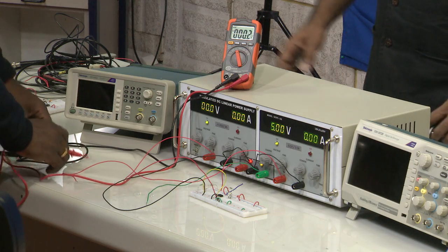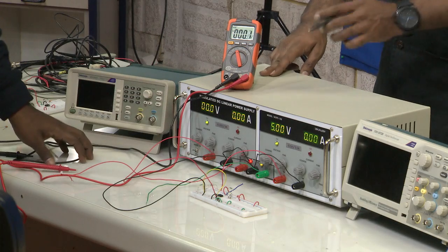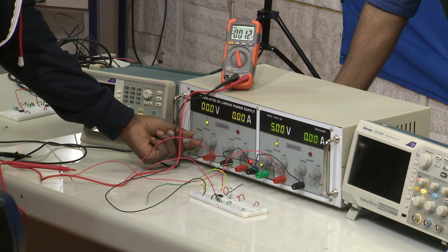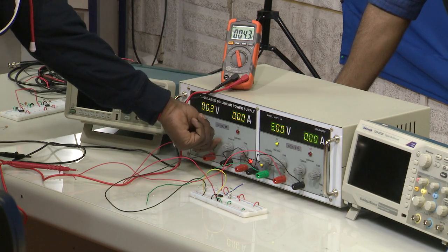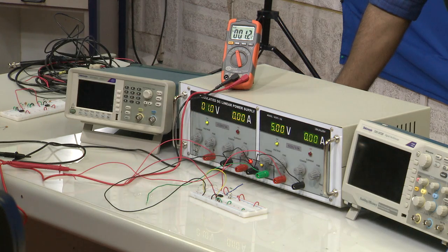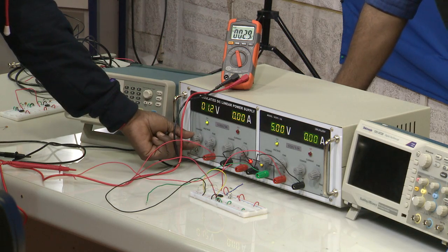Now, let us apply different voltages through the power supply to the non inverting terminal. So, can you please apply? Now, you see he is increasing from 0 slowly, 1.7, 1.9, and we see there is no glow in the LED, right. That means your inverting terminal is still high, which is obvious because the inverting terminal is 2.5 volts, non inverting terminal is 1 volt. So, still V in is less than V ref. When V in will be greater than V ref, then only we can see the output plus 5 volts.